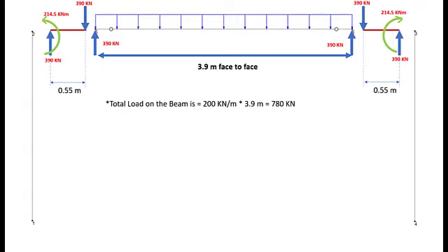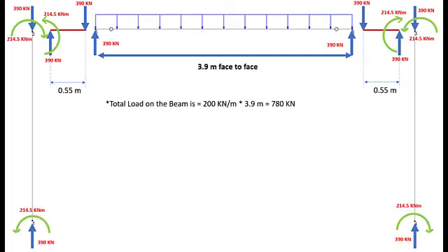The moment would be calculated as 214.5 kilonewton meters, which is equal to the couple developed by the two equal and opposite forces. Now, the force would be transferred to the columns as axial loads and moments on the column, and the free body diagram would be complete with the support developing the necessary resisting forces. So we can see that invoking the master-slave feature in our model would simulate the behavior that we would expect in the field conditions.